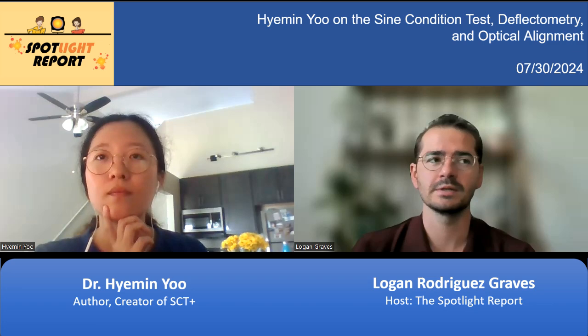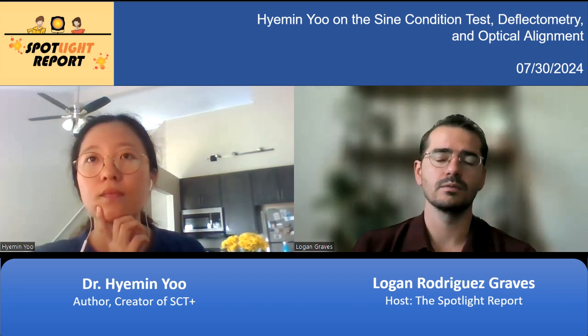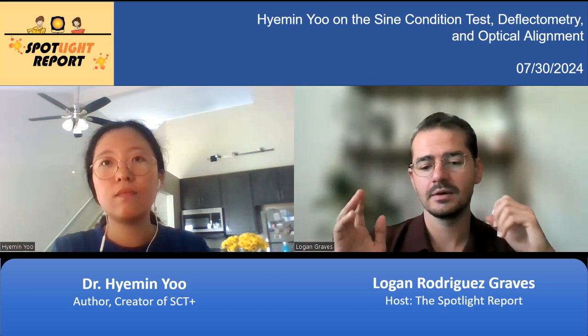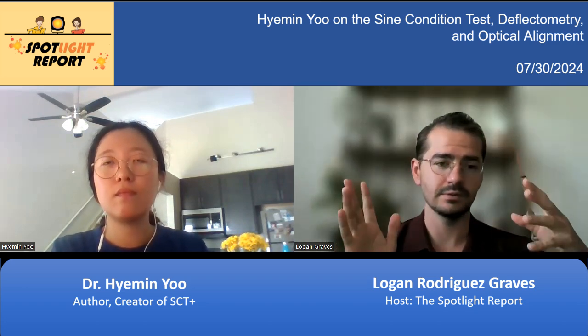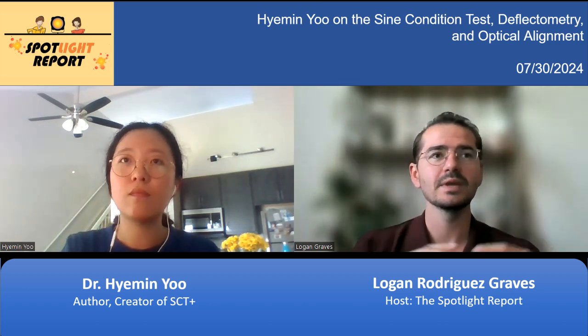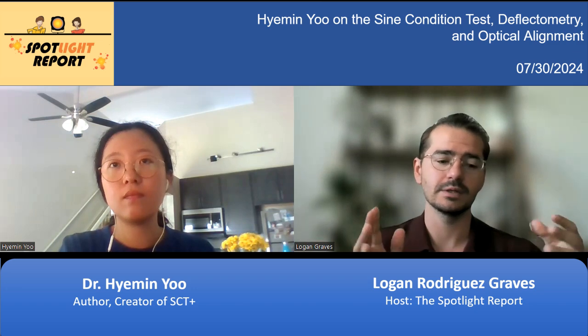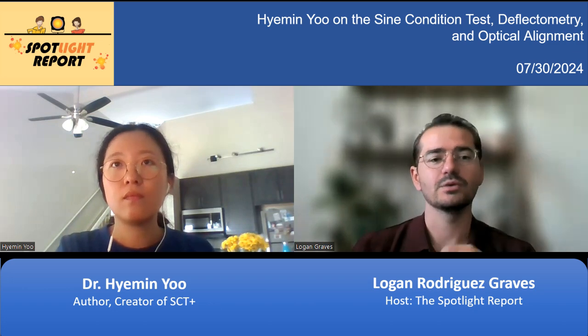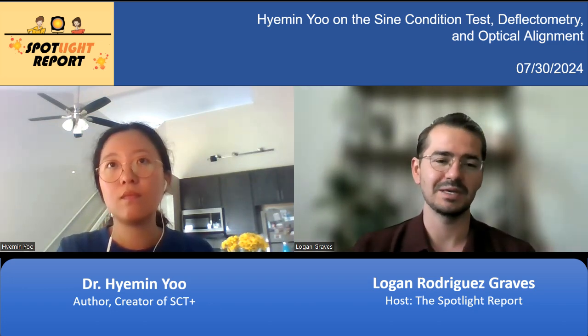I'll give a counterexample that I'm familiar with. I've been familiar with an imaging system that needed to test the distortion across the full field of view, and it needed to test the off-axis wavefront aberrations as well. What that ended up requiring in one modality, with an autocollimating telescope, was positioning and angular input to an incredibly tight mechanical tolerance, submicron, super accurate angular testing.